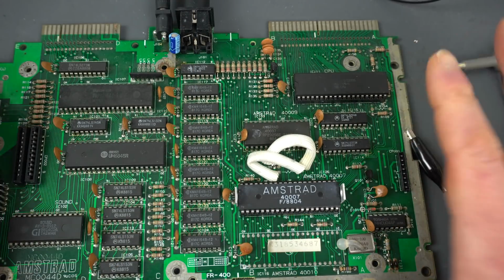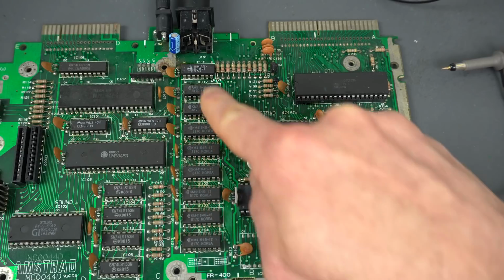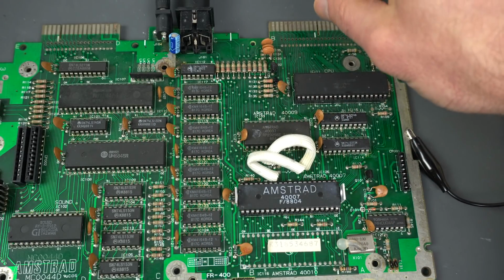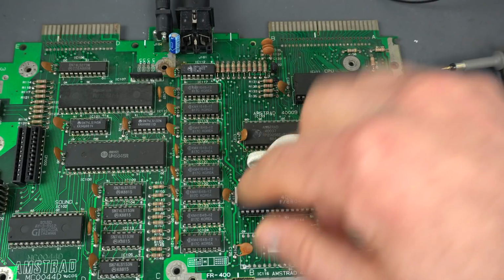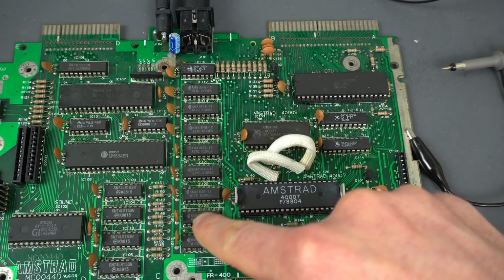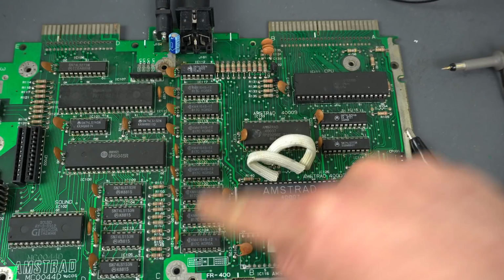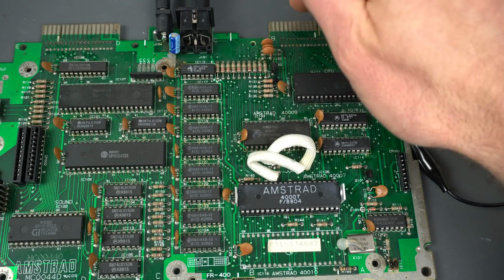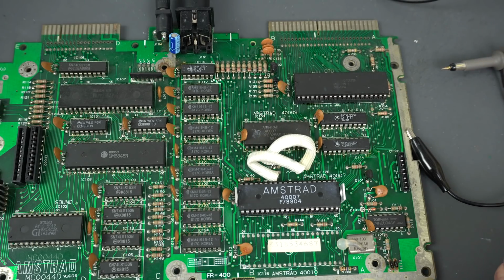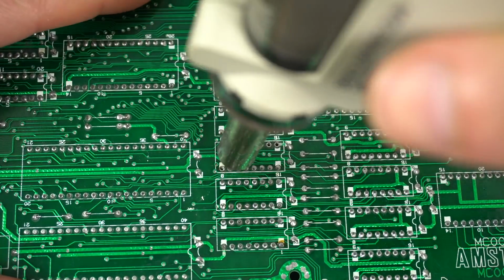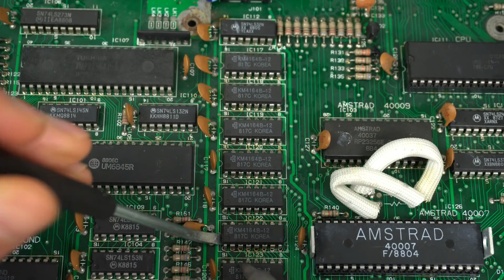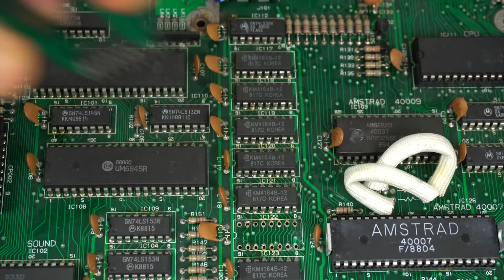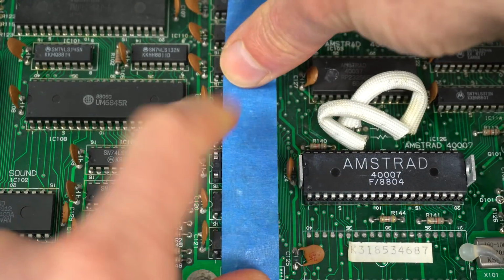However, that's probably not going to fix all our problems because this is just the RAM. And when I try to run the diagnostics programs from the ROM cartridge, it actually doesn't care about the output bit because that one is not connected to the data bus. So in theory, it should have been able to read the cartridge ROM correctly. But you know what? It looks really bad. Let's go ahead and replace it and see if that bit looks better after that, and it may help us along the way figure out what else is wrong.